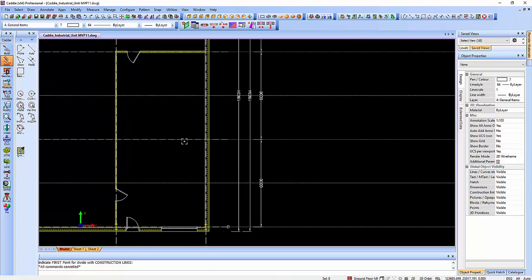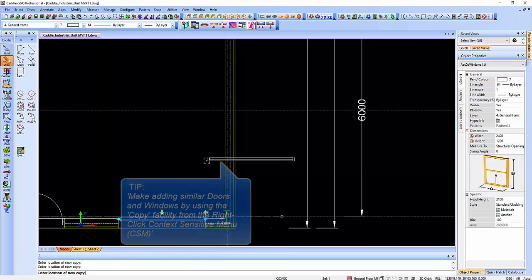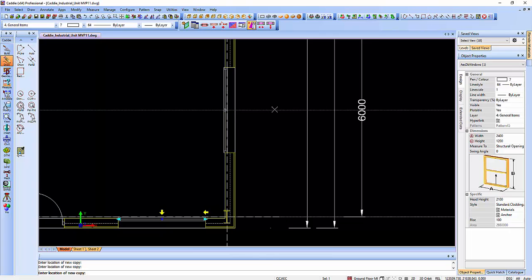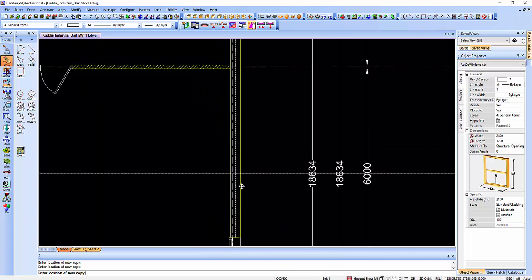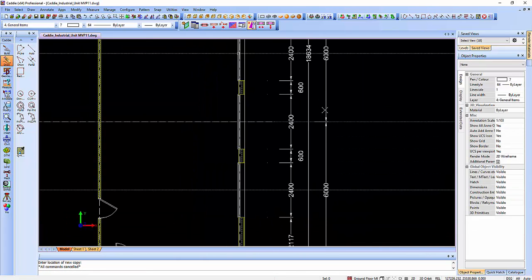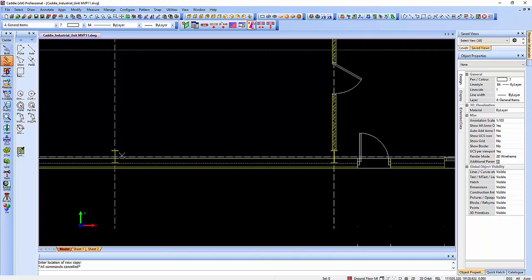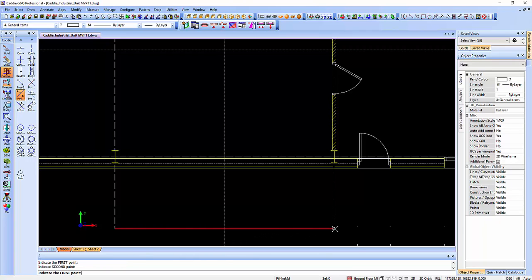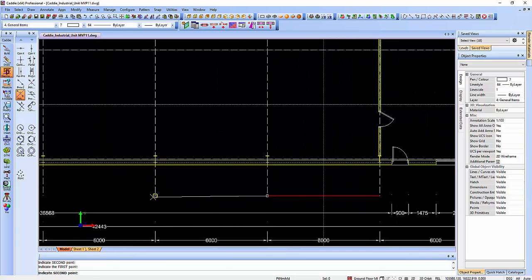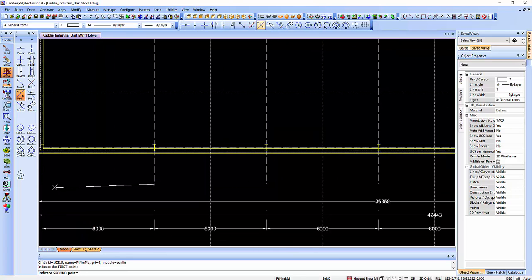Okay, so let's set up a position, so we can literally now just take our window, right click, copy, and then if we choose our snap method, you'll see that it's just dropping those in, complete with the amended position within the wall, and also updating the AEC dimensions as we go. And for the overhead doors, we'll use a similar operation here, but we don't need to divide it into 4. We'll simply use the one on the standard menu here, which subdivides between 2 points. So that's given us the setting out positions for the centres. So you can just drop those in very quickly.